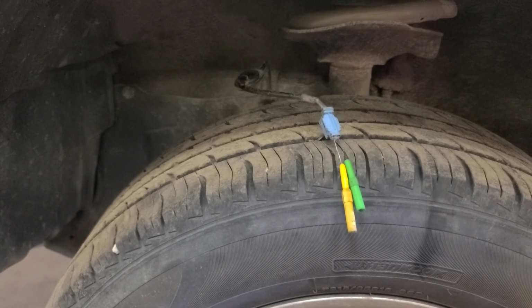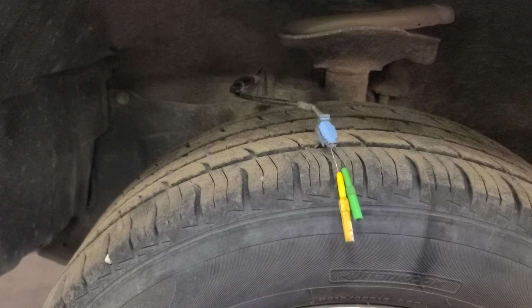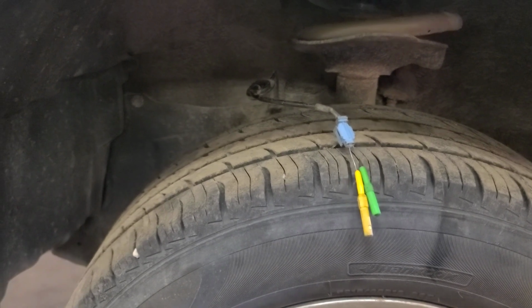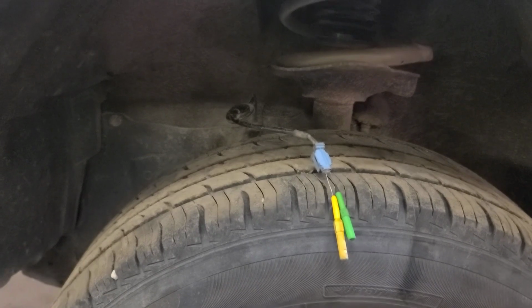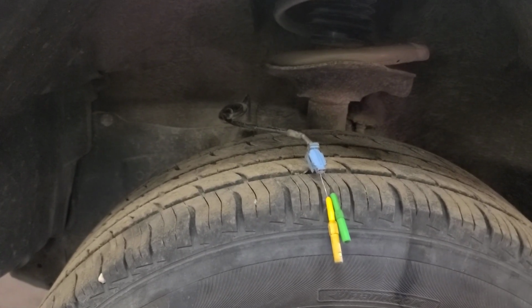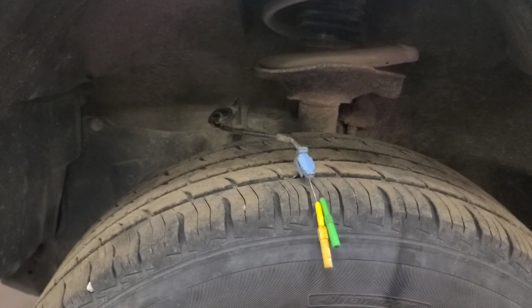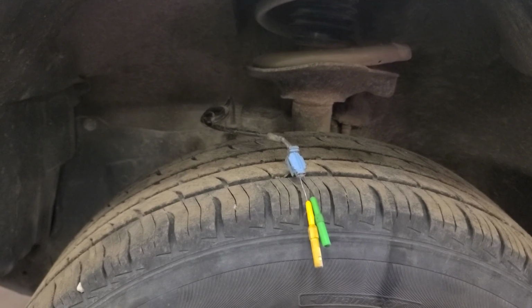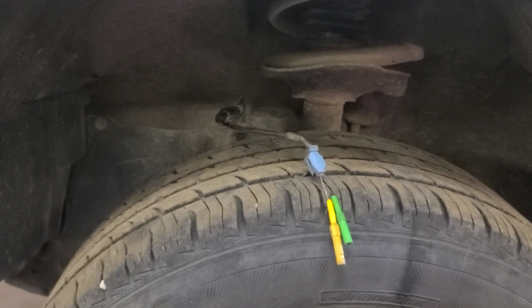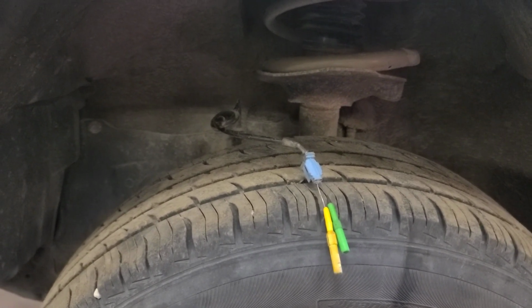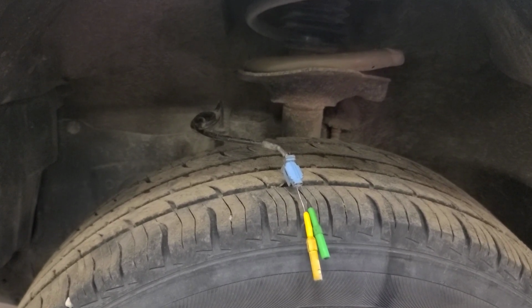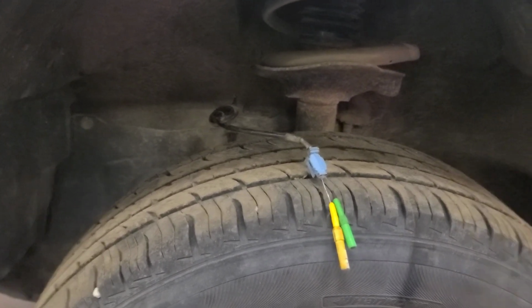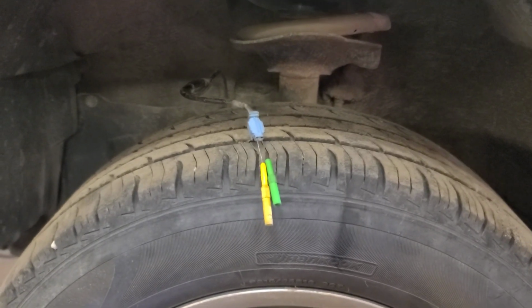The right front speed sensor connector is fairly accessible. So what I'm going to do is run the wires from this speed sensor with a long jumper wire over to the other side and vice versa, and see if it generates the other fault code. If I connect the right speed sensor to the left circuit, and now it sets a right circuit fault code, then I know it's the speed sensor that's defective.